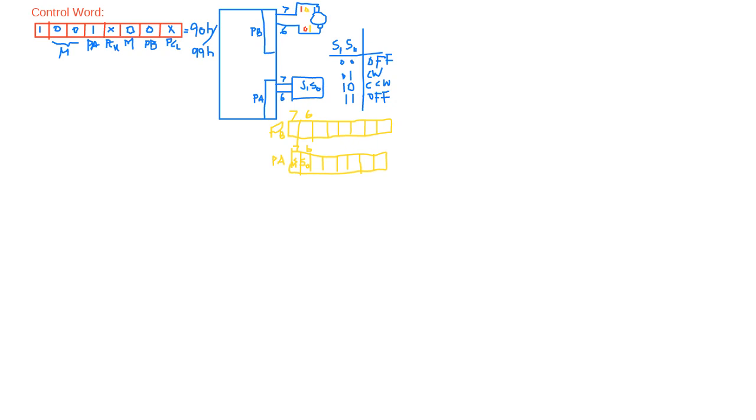Okay, so now it's about writing the program. Okay, let us write the program. .MODEL SMALL and then .CODE. And now we can define variables for the port A, port B, port C addresses. For example, PA EQU 00H,